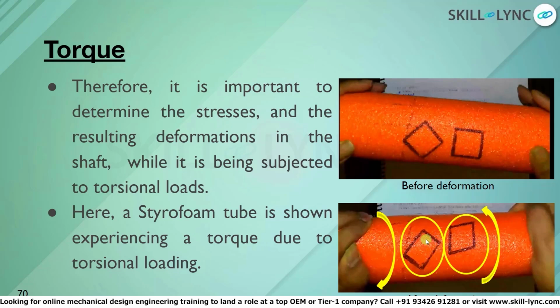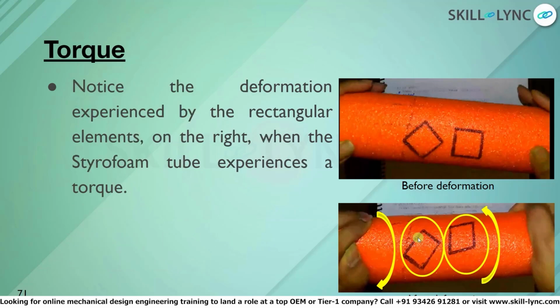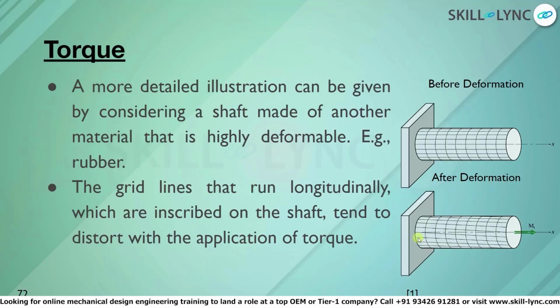stress. But this is exactly opposite to the previous example which we saw in our previous session, which was the elongation of the glove. In the elongation of the surgical glove, we saw that the rhombus was experiencing shear stress and the rectangle was experiencing axial stress or normal stress. Now these are the effects of applying torque to a tube.